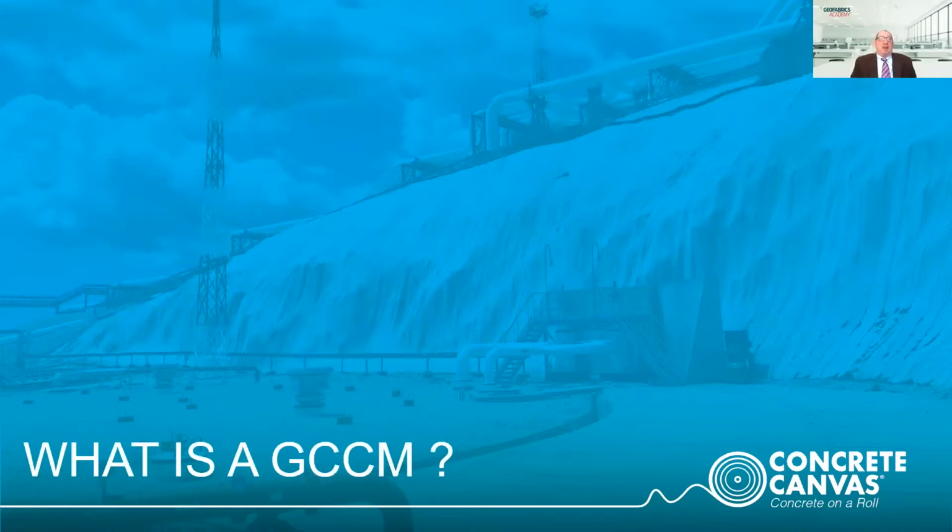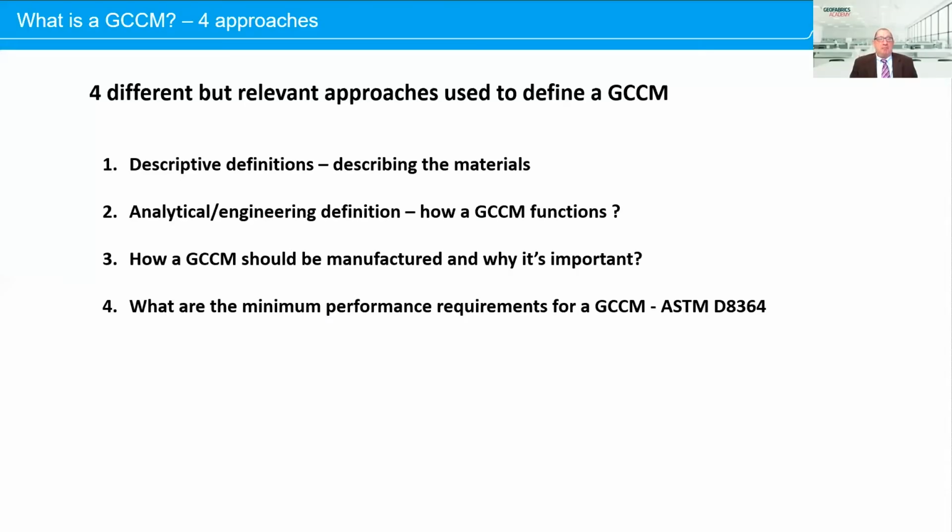Excuse me. So first up, what is a GCCM? As I mentioned earlier, we'll look at 4 approaches. Firstly, we'll look at the descriptive definition, describing the materials. Then we'll look at an engineering analysis of how a GCCM functions. We'll look at how a GCCM should be manufactured and why it's important. And we'll look at what the minimum performance requirements for a GCCM are. That is the new standard. It's about 14 months old now, ASTM D8364.